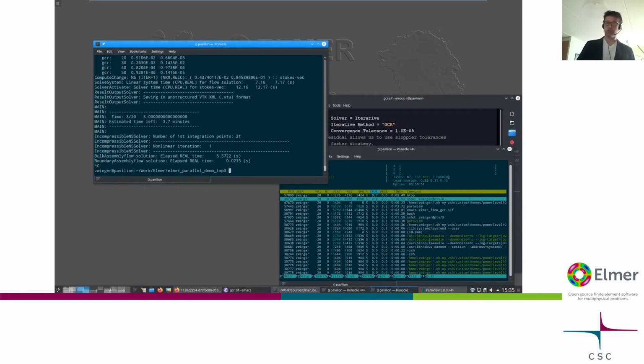So you could also have, now with the serial mesh, a simple multi-threaded run by declaring, provided, of course, you have a version compiled with multi-threading, aka OpenMP, activated. You can declare your OMP_NUM_THREADS to be, in this case, for instance, 6, according to my computer, and then run the case as if you would run it in serial.